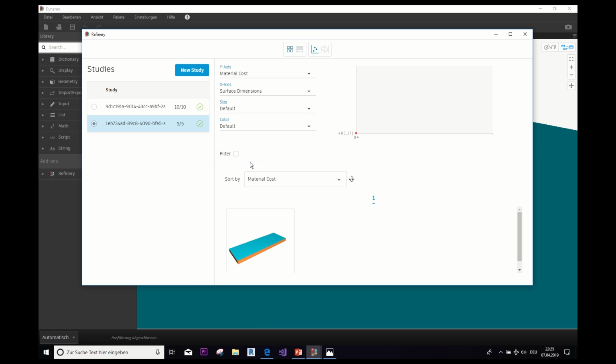So when you work with generative design, make sure to always try out different generation lengths, different amounts of seeds, different population sizes, to see if you can tweak the results a little bit and at what kind of value they stop developing. So enough of this example, let's maybe try something more complicated so we get some more interesting results, right?